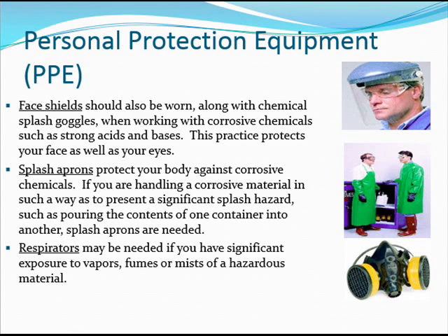Splash aprons protect your body against corrosive chemicals. If you are handling a corrosive material in such a way that there is a significant splash hazard, such as pouring the contents from one container into another, splash aprons are needed. Respirators may be needed if you have significant exposure to vapors, fumes, or mist of any hazardous material.